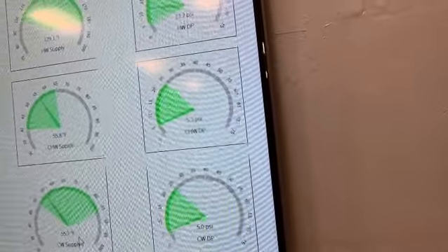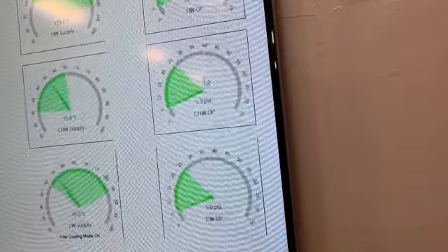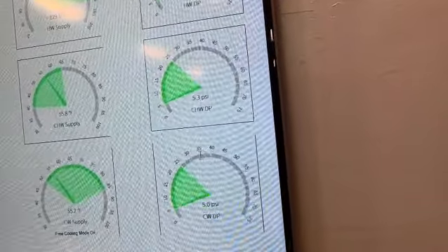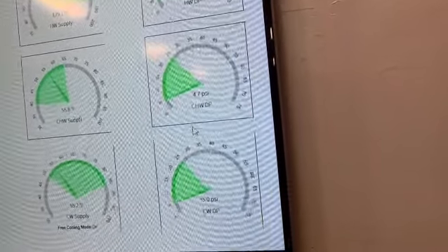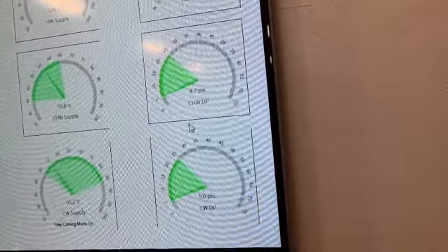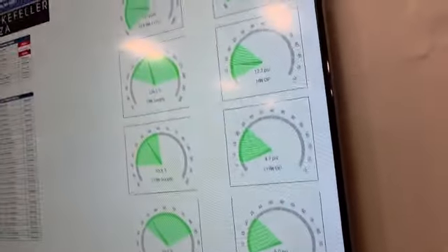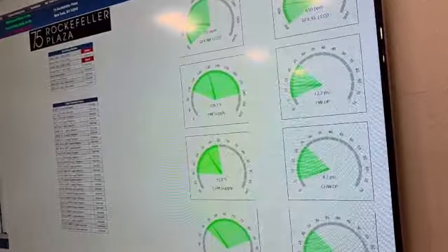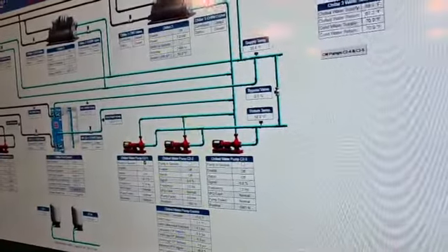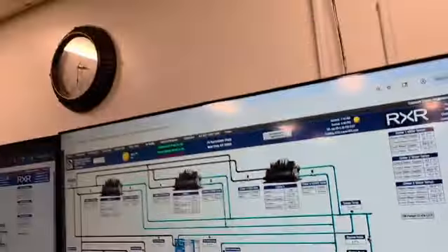And then condenser water supply. You know that, right, from the chillers. It's the same thing. And condenser water DP. Exactly the same thing. This is how much pressure difference there is between the water that goes into the device and the water that comes out of the device. Got it? Okay. Now let's go to the chill plant, right? Right now the chiller plant is off, but this is what we were talking about, right?